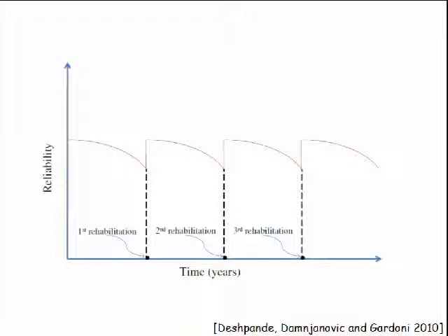But ideally, if we are interested in carrying on with reliability-based approaches, we should do it this way: there is a reliability value, which is good. The reliability value will subsequently fall, and once it reaches a terminal value, then I provide an overlay. That means the overlay is decided from the overall reliability consideration, because in that way you are able to combine the structural issues and functional issues, and consider many distresses together in terms of reliability.